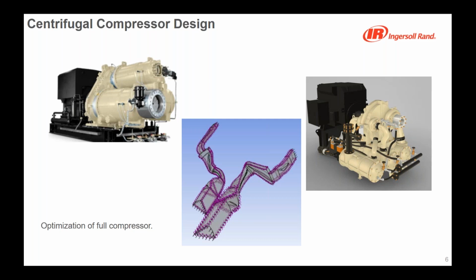So you can reduce your compressor, actually your two stages machine, to a single sector per stage, and you can have the two of them running in the same simulation, connecting one to another with a set of equations to transfer energy, the pressure drop, temperature and so on. So those are the main challenges. You can go from the single stage to the multi-stage machine.